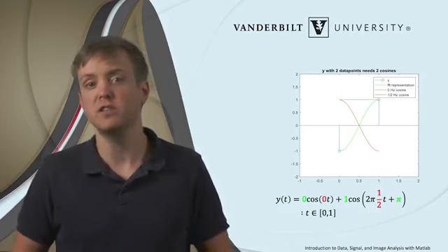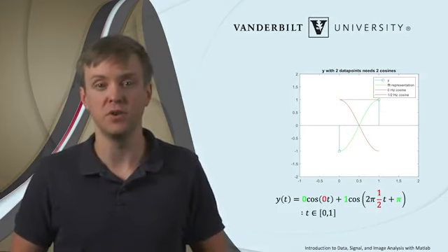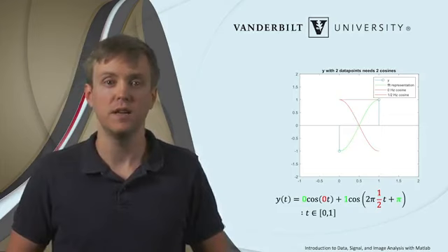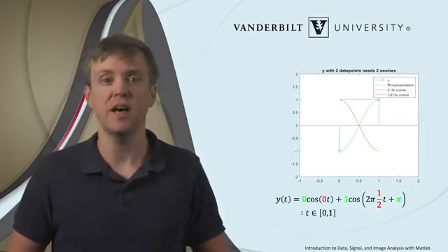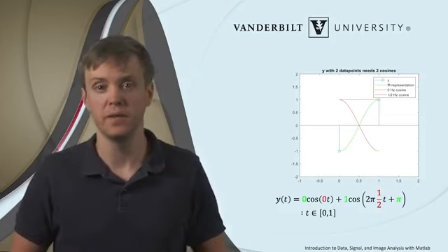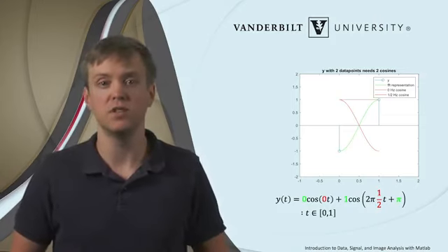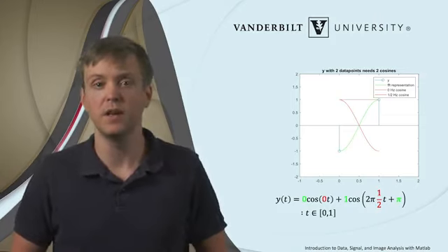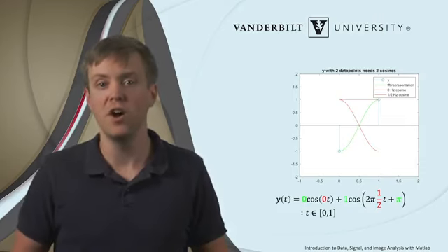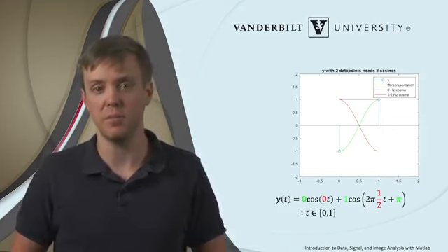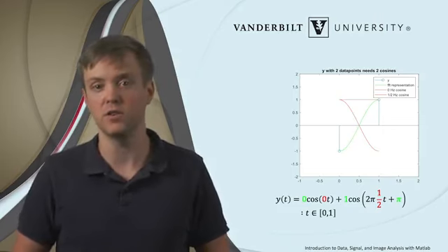The 0 frequency term captures the average value of our signal. Here, our y is equal to -1 and +1, so it has an average value of 0. But if instead y was equal to 0 and 2, our whole plot would shift up by 1, and we would want 1 of cosine 1 plus 1 of cosine 2 phase shifted by pi to approximate our signal y.